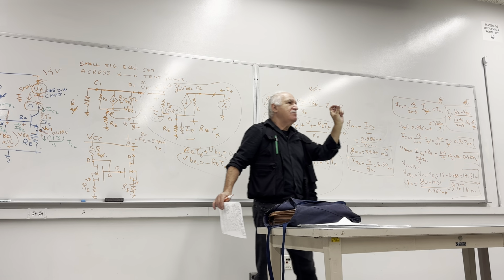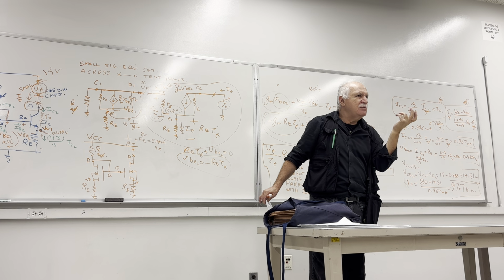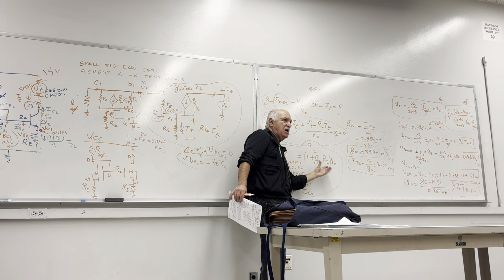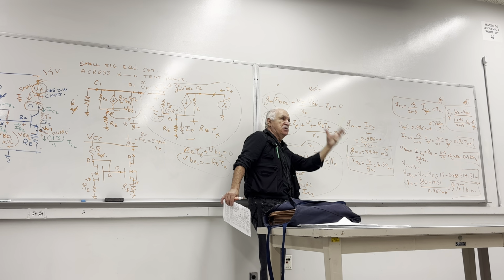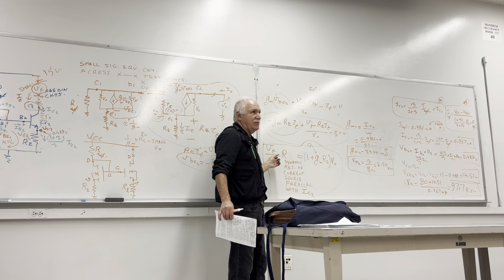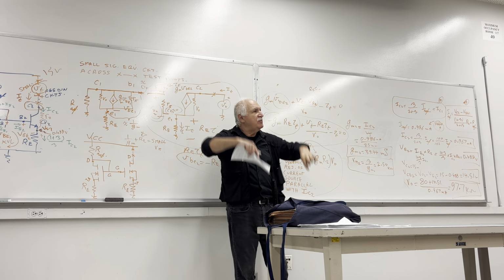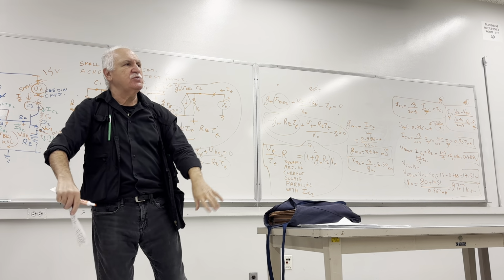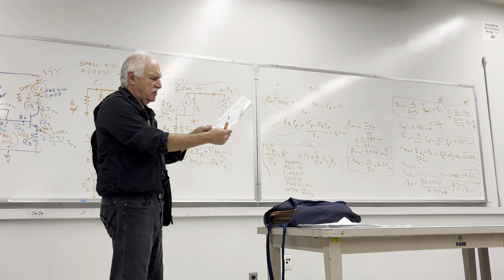When GM multiplies a resistance, it looks like a voltage gain. Do you see that? GM times RC, like a voltage gain. So you've got a voltage gain type of product here, which is multiplying the RO. So we get multiples of RO for the dynamic resistance, not just the RO in the previous current source that we had. In the previous, both emitters were going to the ground. So this example is showing you.